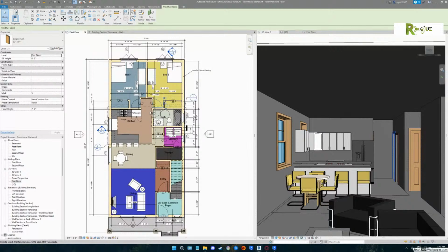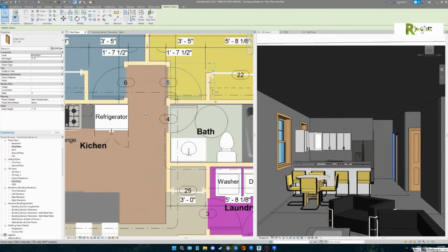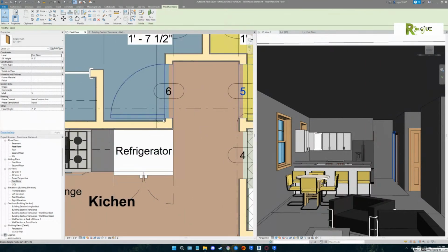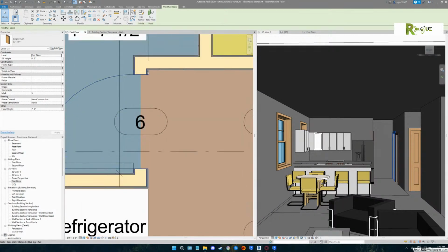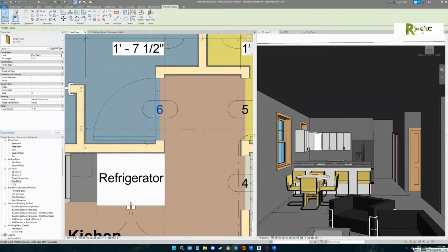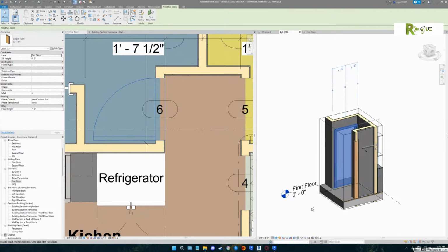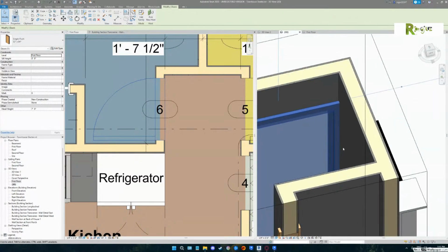It looks to me like the bedroom doors are pinched. It looks like your little hallway back into there might need to be deeper, or your doors might need to be narrower, because I'm seeing that you barely got room for the 2-inch stud and the trim. You also had that little gap, exactly right here. Pick that one door. Type in BX. Now rotate yourself around. See that trim that's going down the side? It runs into the wall.